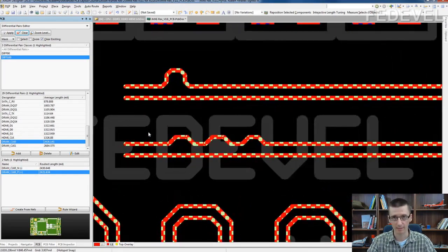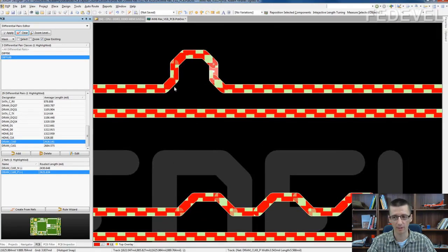And what makes the big difference when you are doing length matching are these parts here. That's why I call this a full wave. A full wave will have this corner, this part, this corner, this part, corner, part, corner.